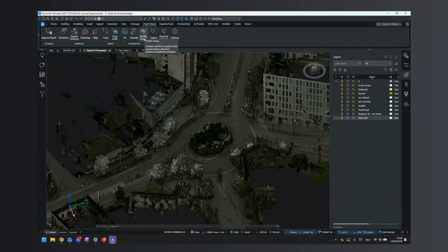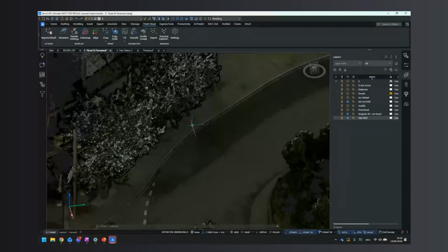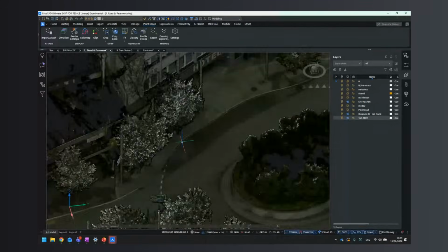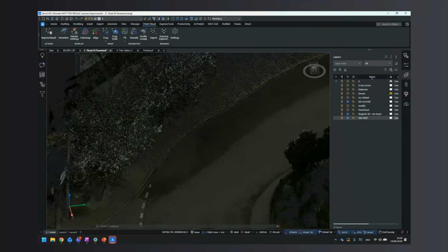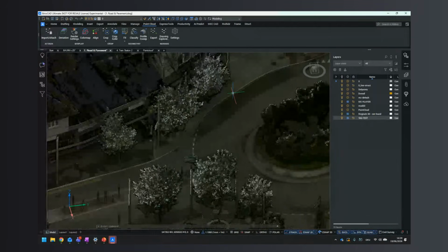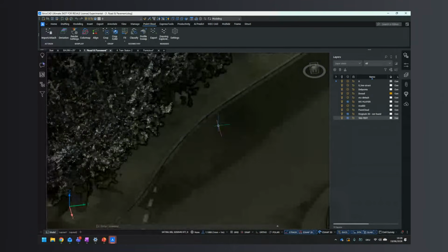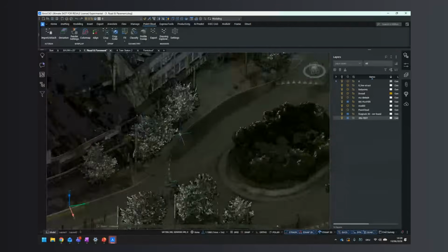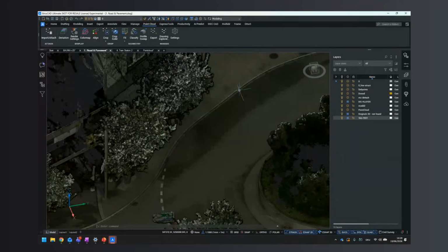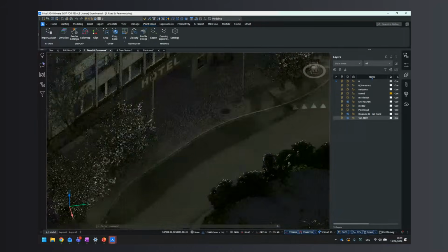This is a new addition that makes the life of surveyors so much easier, because if you're working with infrastructure projects, road creations, train, railway stations, you will need eventually to compare your design with the reality, or even capture the reality and create a model out of it. So what is absolutely essential in this case, so we can see the roads and the pavements, we need to trace the break line of the pavement in that scenario. So let's see how that looks like.